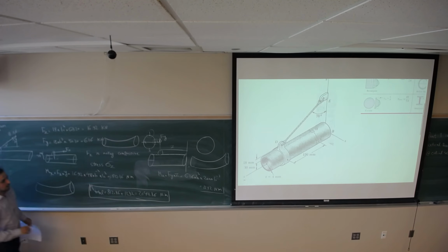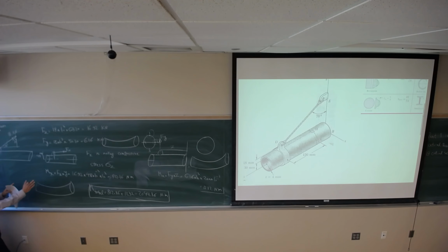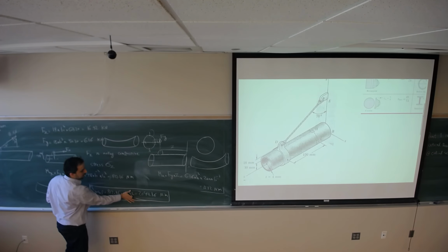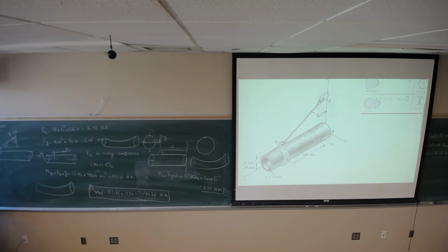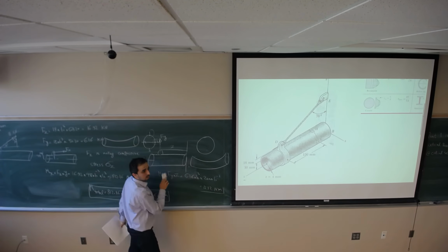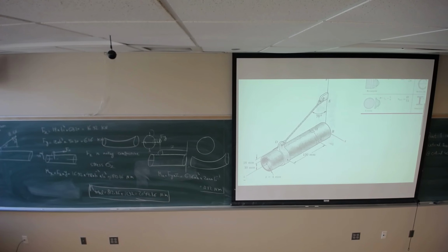So now, any questions so far? For the rest, I'm gonna find the normal stress due to the compressive load and the bending moment stress due to the bending moment, then add them up to see what would be the maximum normal stress. I just wanted to save time, but it's better that we test it on the small number. What I'm saying is it's going to be a significantly small number compared to the normal stress.